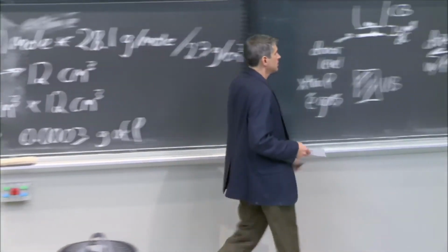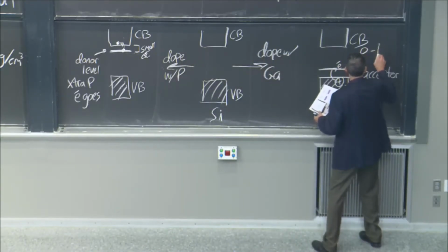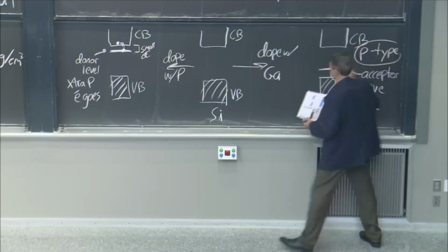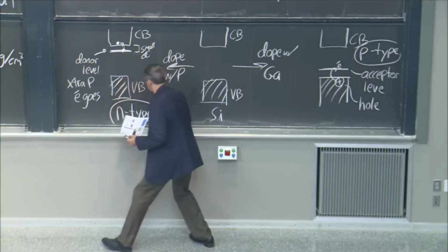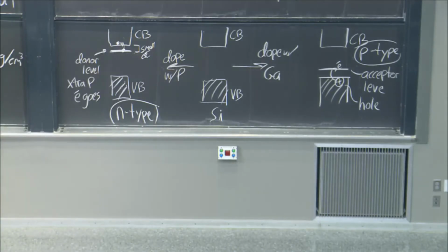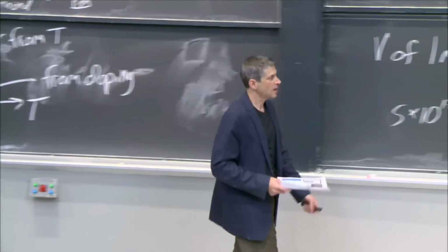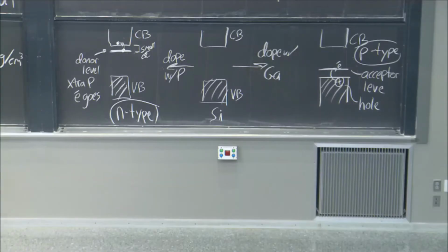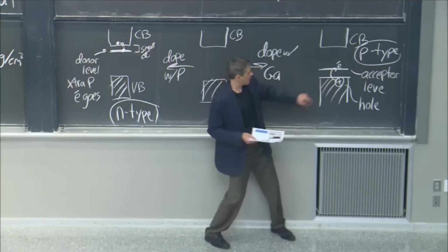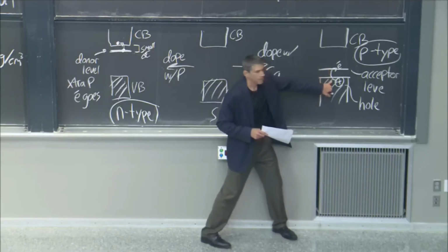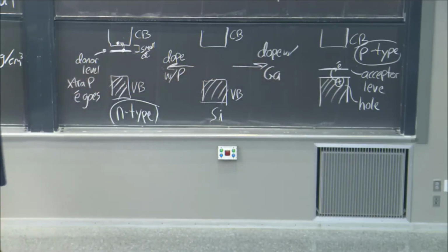And that's really important. So these are two different types, and you can imagine the brilliance of the naming. These are p-type because it's a positive charge, and these are n-type because it's a negative charge. Those are n-type semiconductors. What does that mean? I've used a little chemistry, sprinkled a little something with extra electrons. It's got negative charge in the conduction band. P-type, P means positive. It means that I have introduced states here because I needed an electron. I say, I need an extra one. I'm going to grab it from somebody, I don't care who. And so you create a positive charge in the valence band that can conduct electricity just like a negative charge in the conduction band can.